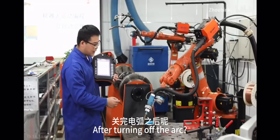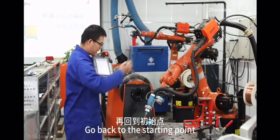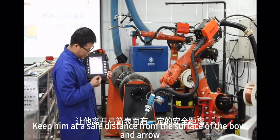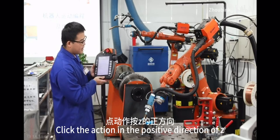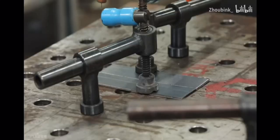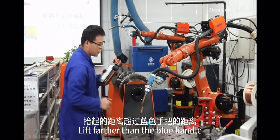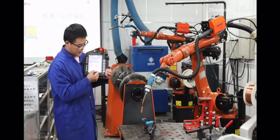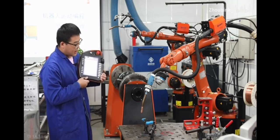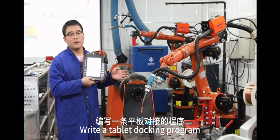After turning off the arc, you also need to let the robot leave first and go back to the starting point. So, keep him at a safe distance from the surface of the plate. Click the action in the positive direction of Z. Power on first and press the positive direction of Z. Lift it up, further than the blue handle. Just do it. OK, it's the instruction. OK. So this is our live demo: writing a tablet docking program.